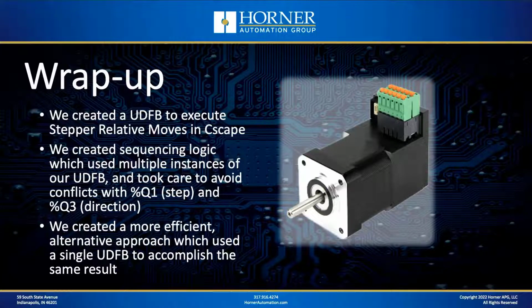We created sequencing logic to use multiple instances of a UDFB in order to execute a whole sequence of moves. And then lastly, we created a more efficient alternative approach using a single instance of the UDFB to accomplish the same thing. So I hope that you got some good out of today's show. Even if you're not necessarily going to be executing stepper moves anytime soon, hopefully you saw a good creative way of taking some logic and turning it into a UDFB, and then a couple different approaches to executing a sequence when part of the sequence is executing a user-defined function block.